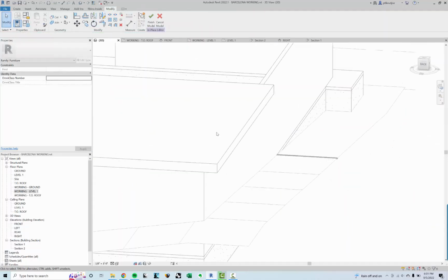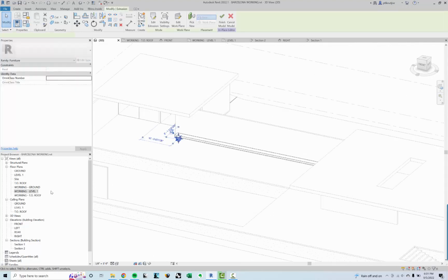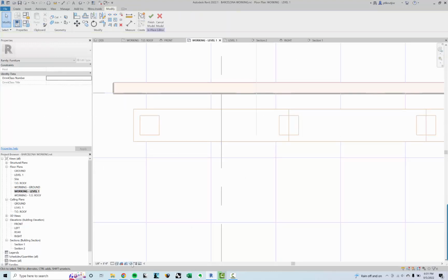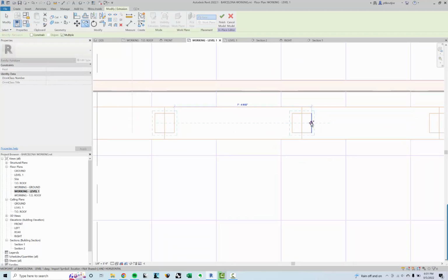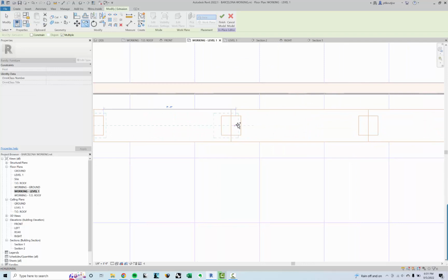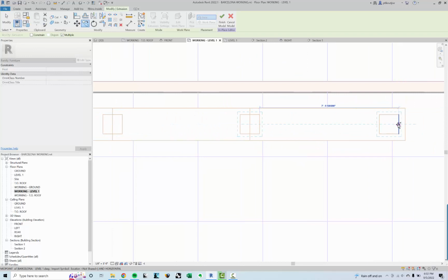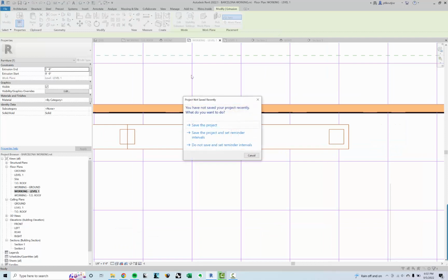And then I can actually come in, grab that, and let me see if I change this to, I want to try to just quickly change this to wireframe so I can grab that. I can actually copy that element within the family creation so I don't have to model it over and over again. All right, so let me change this back. Then I click Finish Model.